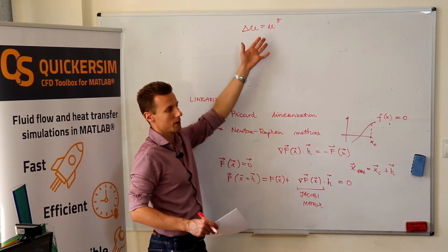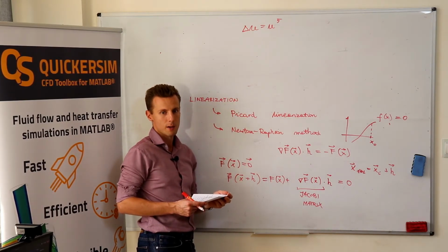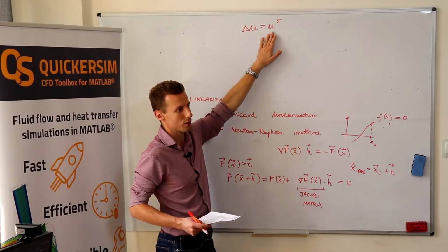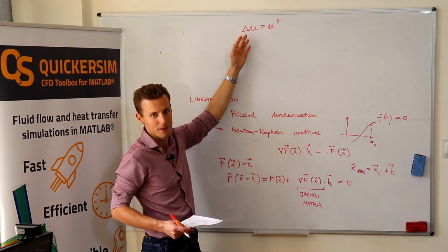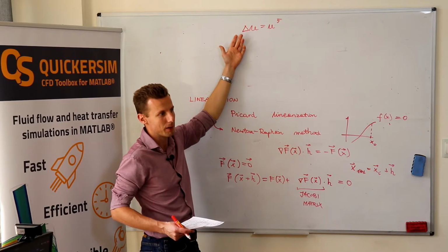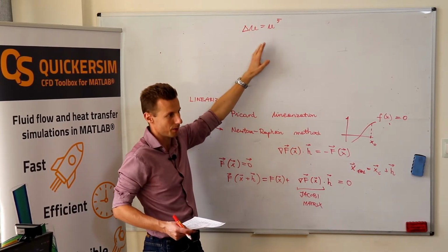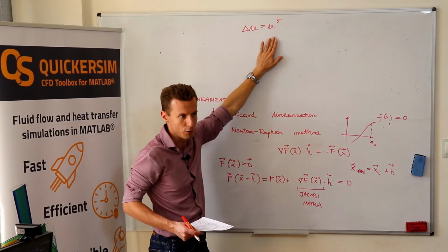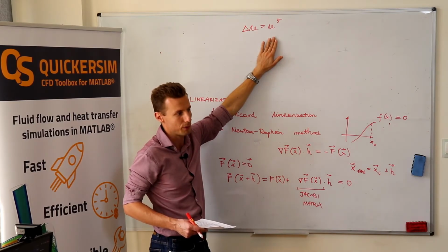Well, the problem is nonlinear, so it doesn't fulfill the nonlinear equations. But, well, you got already some values, so let's calculate the source term. With this new source term, let's solve the problem again. Then we've got some maybe better approximation. Let's plug it here again, and so on and so on. Nice. The problem is that if it's highly nonlinear, you're much more likely to diverge from your solution than to converge.